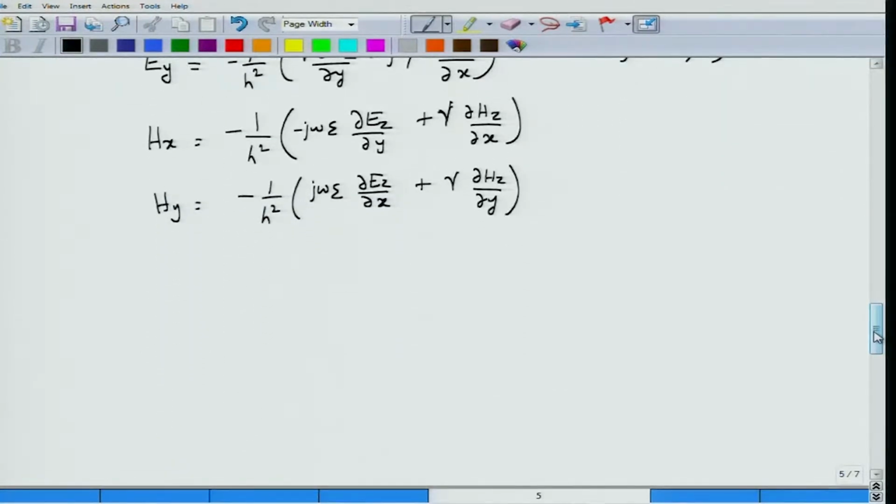So the objective of getting the transverse components in terms of longitudinal components, and the relation between the two, has been achieved. Okay, what do we do from here? Where do we go from here? First of all, let us see what possible modes we can obtain. Let us first try if we can obtain the TEM mode.